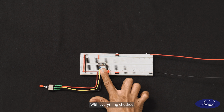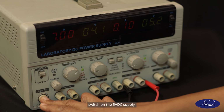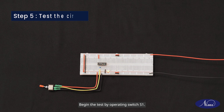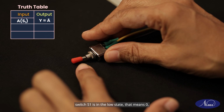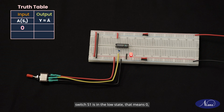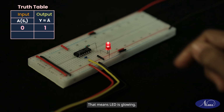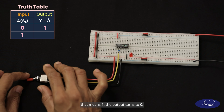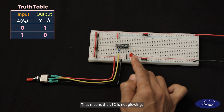With everything checked, switch on the 5-volt DC supply. Begin the test by operating switch S1. Check if the toggle switch S1 is in the low state, that means 0. The output turns to 1. That means LED is glowing. If the toggle switch S1 is in high state, that means 1, the output turns to 0. That means the LED is not glowing.